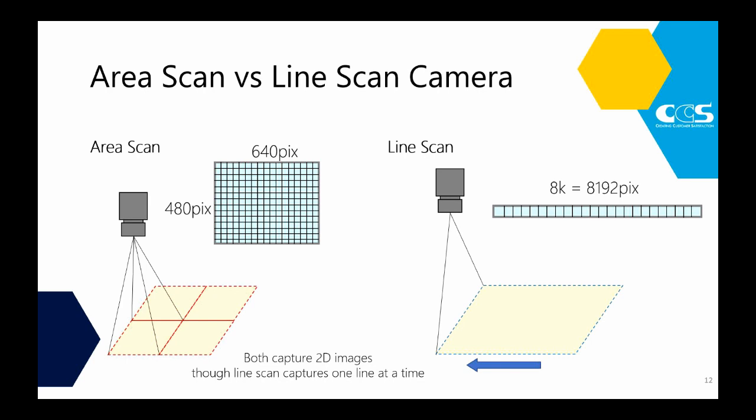I've installed a line scan camera in between a conveyor where we needed to look at the bottom of the sample, and there was about 2 inches between conveyors that the sample moved over. We had a line scan camera looking up from the bottom, so we were able to inspect the bottom of the sample without having to flip it over, even though there's only a 2-inch gap. The downside is your object has to be moving. If it's not moving, you're just looking at one line image, and that's not going to get anybody any data.